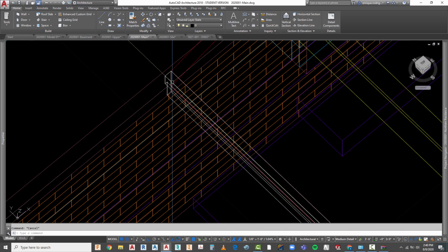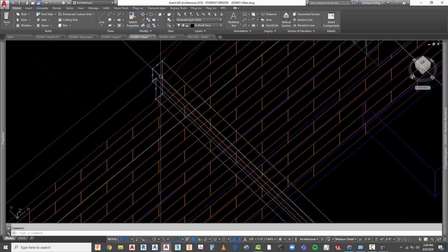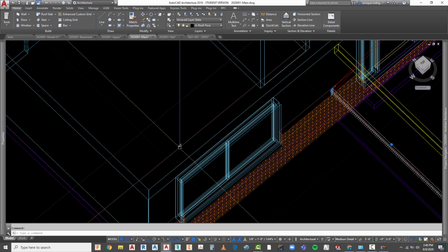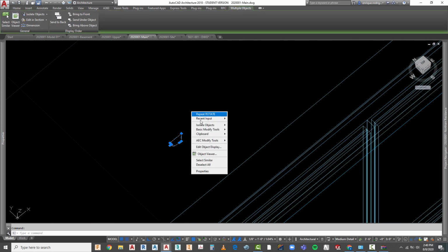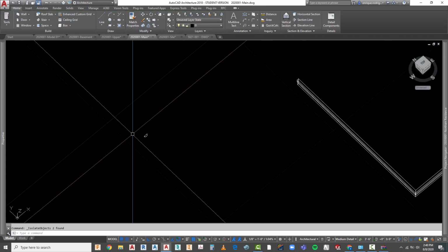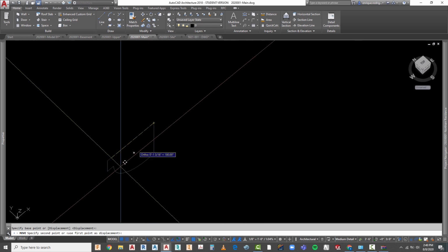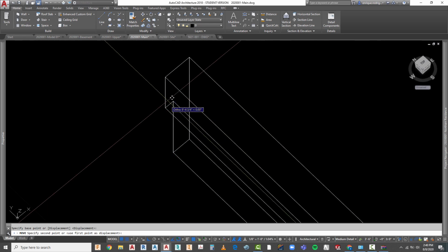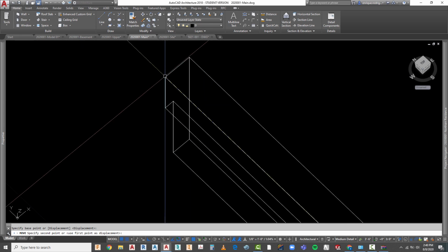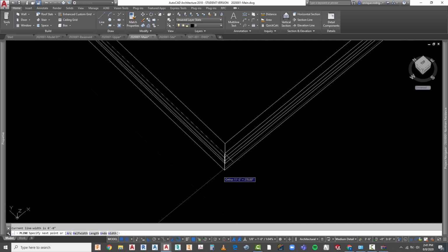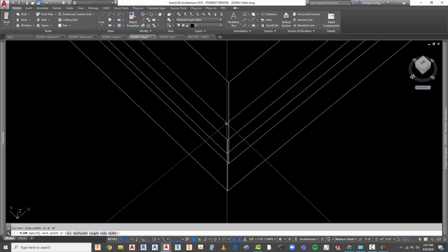And what I'm going to do this time, I'm actually going to use the edge of our fascia board, which was done correctly, and use that as where my path is going to lay. So I'm going to isolate those objects. I'm going to move my object to where I intended it to be also, and this is something we could have done with the other one. I'm going to go to layer 0, or any one of the layers that we've created, and create my polyline from that point, and I'm going to select it right at the edge of the piece. I want to make sure I'm selecting the right corners in here.